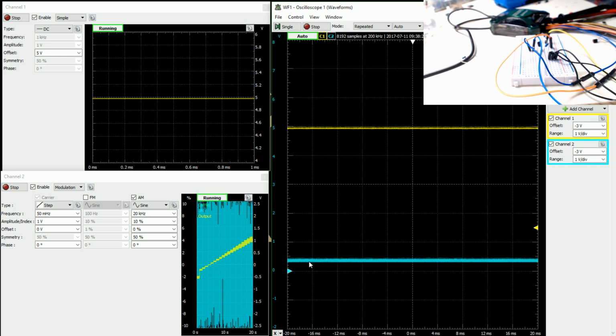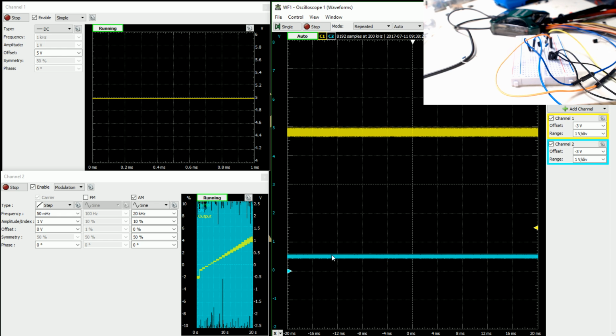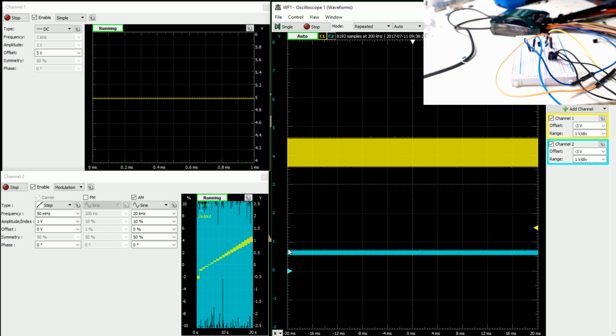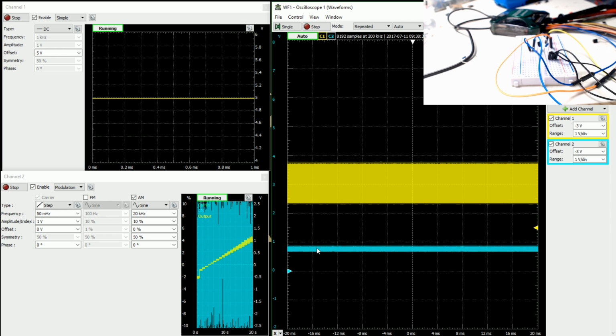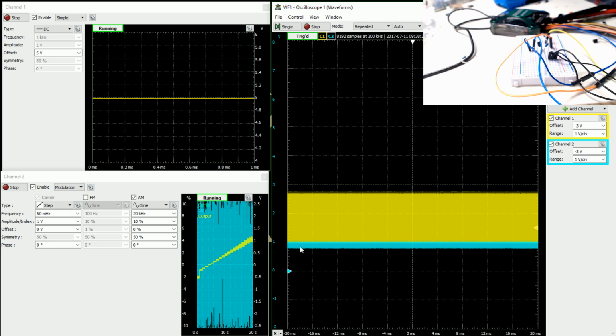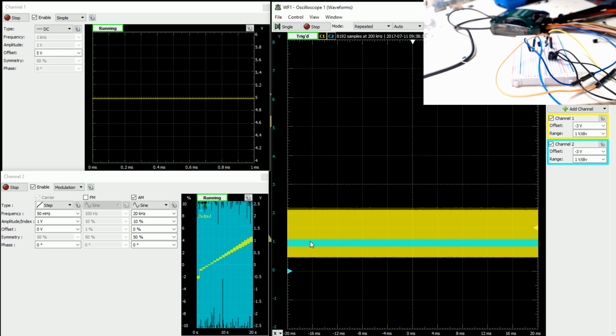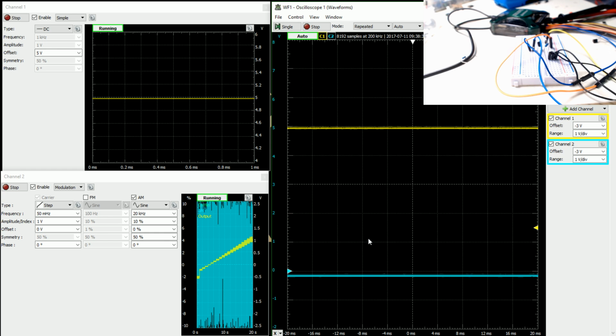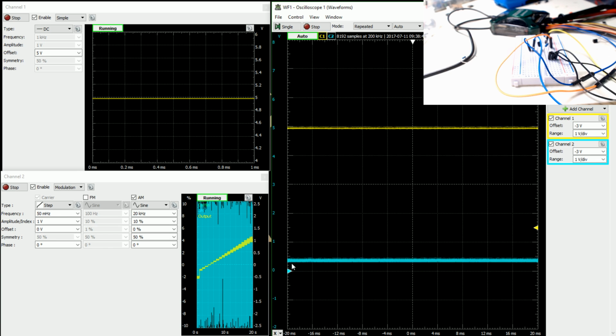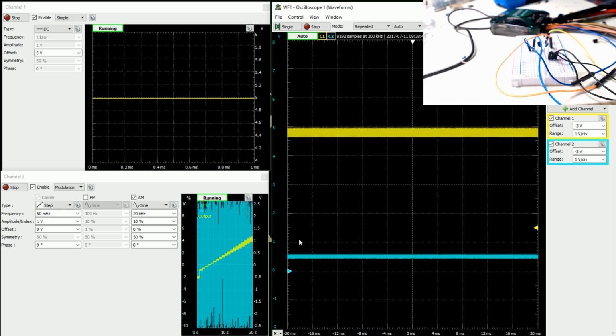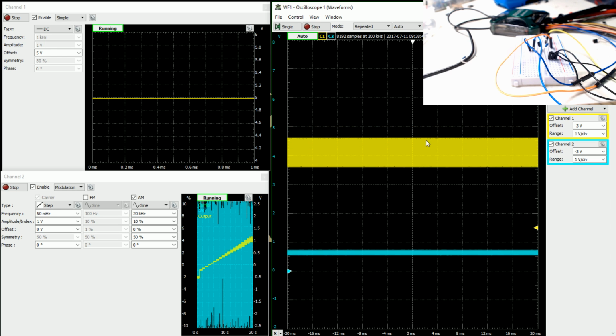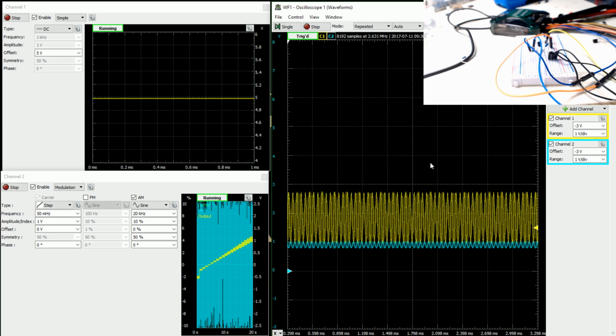You see, this is the signal that's getting added onto the base, right? So this is the base signal that's happening, and you see that it actually looks like the same signal the whole time here. The thing that I don't understand is it looks like there's no offset. Okay, so if we set an offset here, it's starting right about 0, and then it's creeping up to about 1 volt. So it's actually never overloading. Let's zoom in a little bit more. We should actually be able to see some of these sine values.